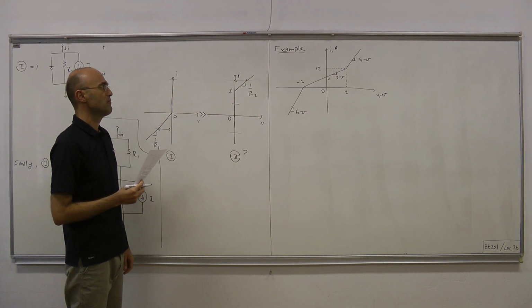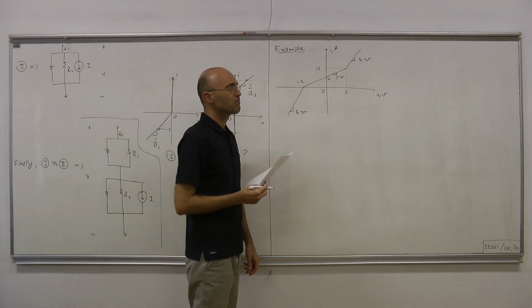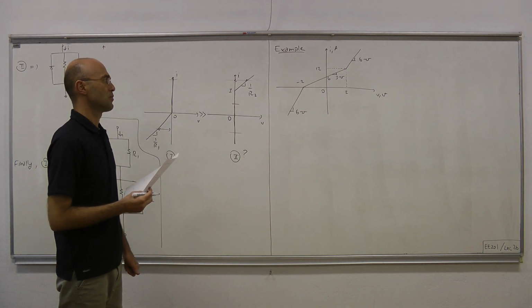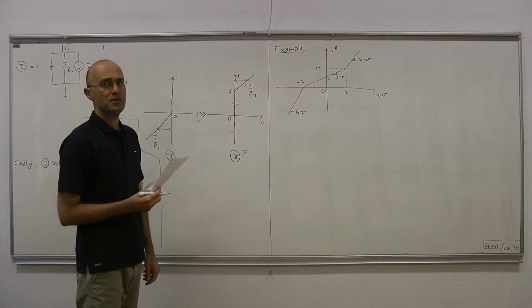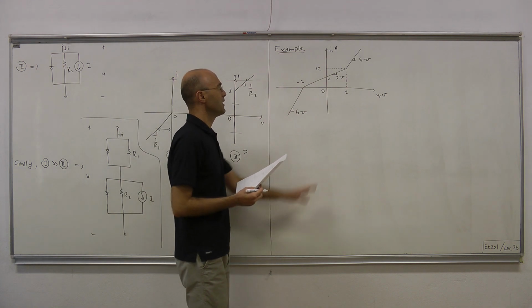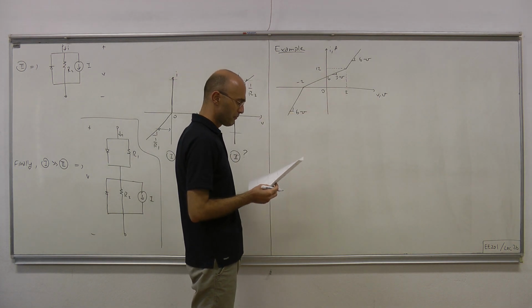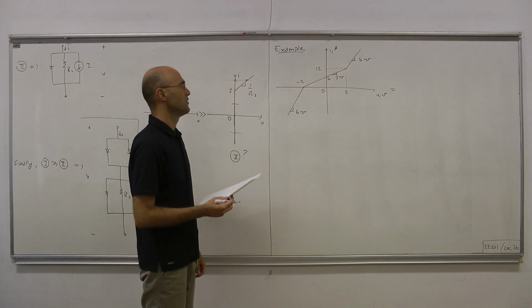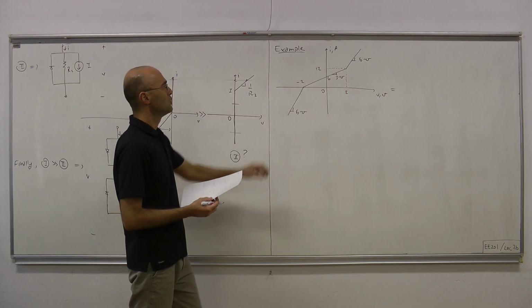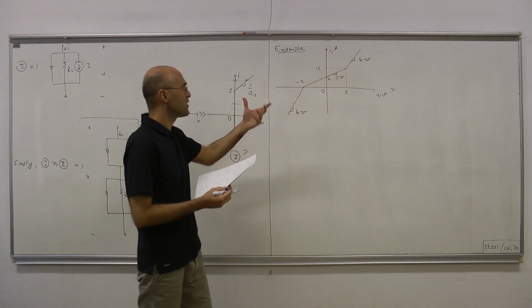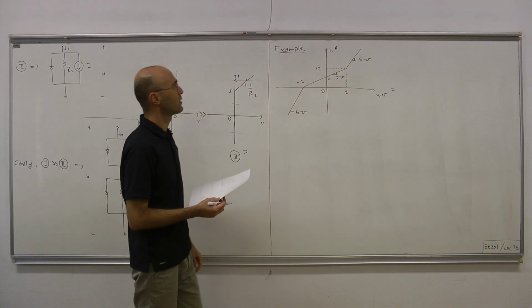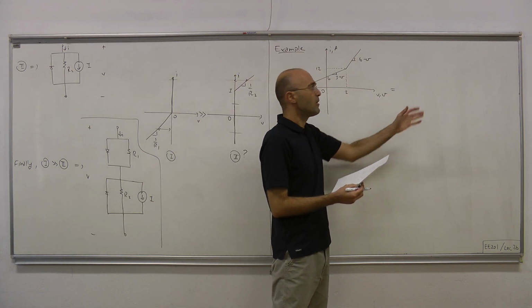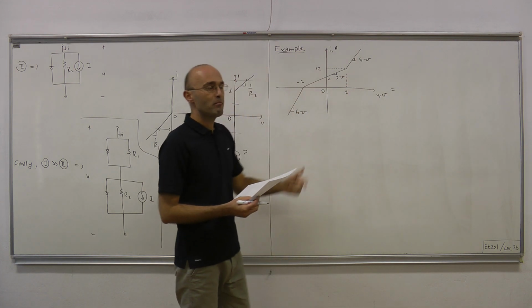Okay, so let's figure out a one port that contains diodes, constant sources, and LTI resistors that would generate this IV characteristics. Okay, so let's begin by decomposing. In synthesis, one way to go is we decompose a complicated curve into simpler subcurves, and be careful about whether to add them in series or parallel.